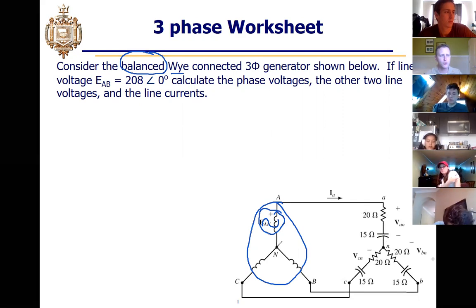This point that's neutral, similar to how we had grounds in our single phase this whole time, we can think of as kind of like that ground that connects these 2 points with a wire. And what that allows us to do is to draw a single phase equivalent.